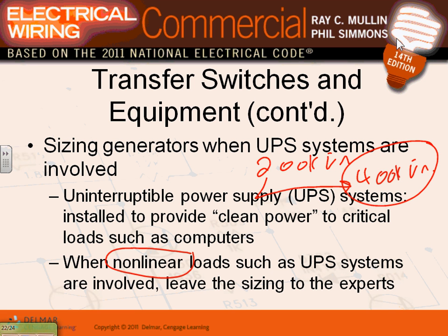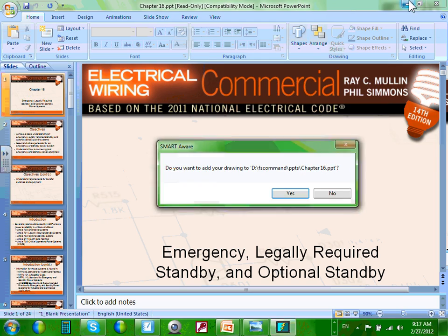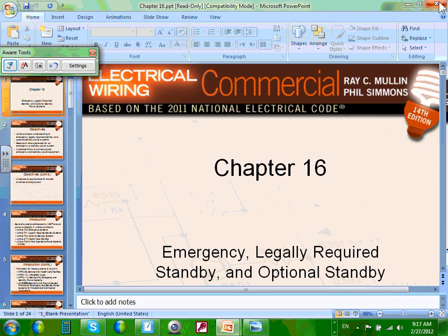You plug them in. Every time you have a UPS or VFD or soft start, the software will actually add more load, to add more size to the generator so it can handle these ugly situations. Okay, I'm going to show you a couple of pictures here.